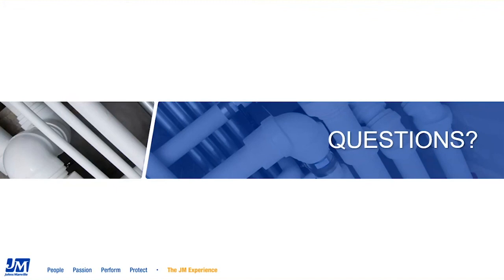So our final question, I'm going to send this one over to you again, John, and that is, with an outdoor application, is the pipe wrap compatible with heat tracing, with a heat tracing pipe warming system? Absolutely. The Microlock HP can be used with heat trace, either a wrap or a wire type heat tracing.